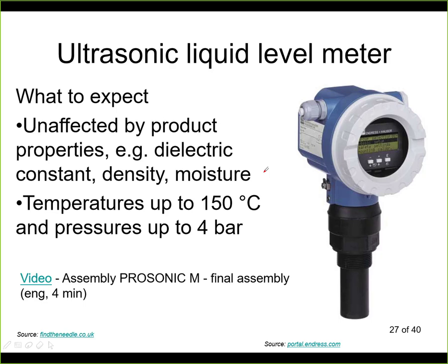On the other hand, if the interface is with a foam, for example, then this will not work properly, because the foam will attenuate the ultrasonic signal and hence will not get the reflection that we are expecting. So the ultrasound meter is not suitable for foam on your liquid. So if you again measure the liquid level in the tank with beer, then it's not a good idea to use ultrasound, because the ultrasound will be attenuated by the foam that you have on top.